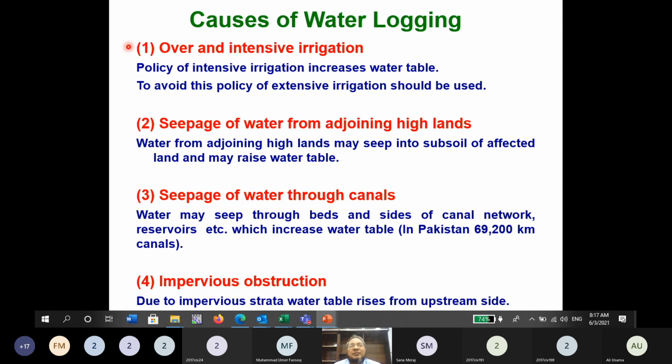That's why whenever we provide irrigation projects, in an irrigation project we also keep the provision of a drainage project. So irrigation and drainage are very compulsory, because artificially you are supplying more water to the lands, which was not a natural phenomenon. So definitely that has to raise the water table. So you also need drainage, so that the excess water can be drained somewhere.